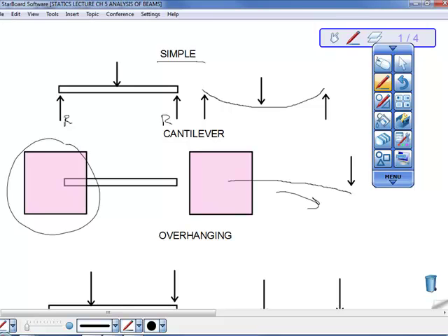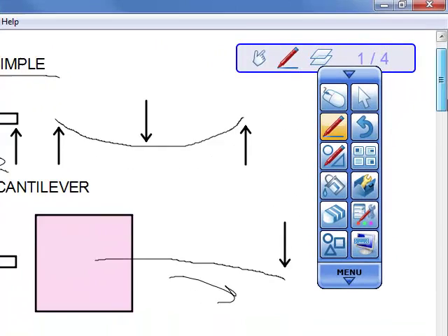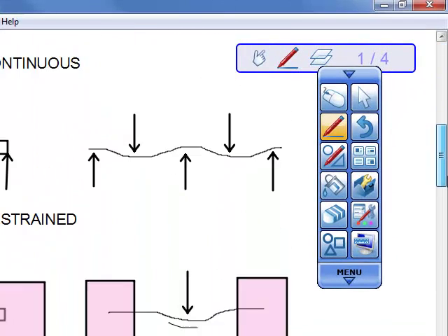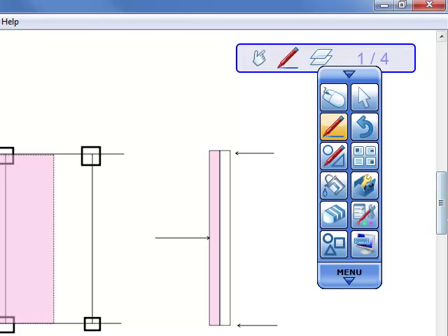Distributed loads are uniformly distributed. And that's kind of what engineers deal with a lot more, I think. I mean, there's concentrated loads and distributed loads, but a distributed load, as I've shown here, you have your columns in your structure, and then you've got your beams, your girders and your beams are these lines. Then, for instance, in this room, they may design it for 100 pounds per square foot live load. That's a distributed load.